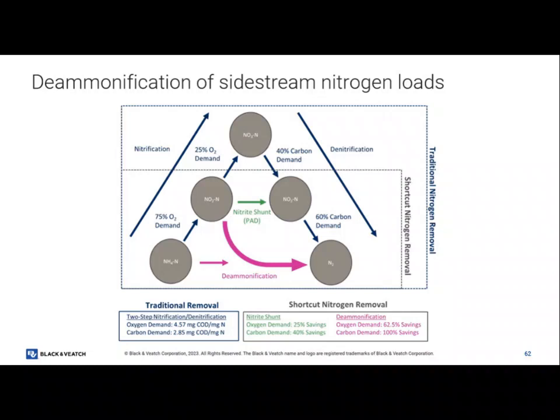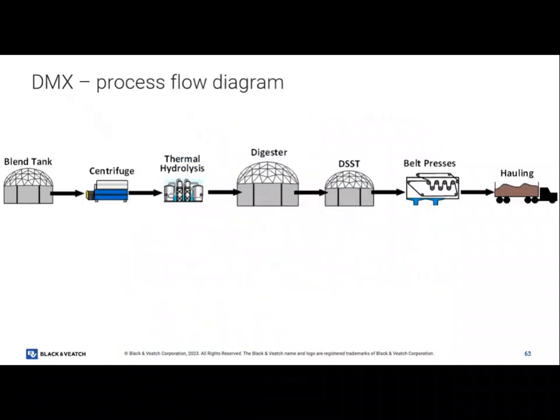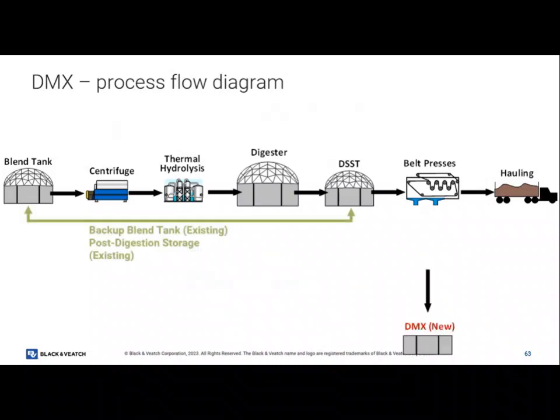When we talk about SRTs of this organism, normally we're talking 10-day SRTs in aeration basins. We're talking 60 to 100-day SRTs for these bacteria to grow. They're just very slow growers because there's very little energy in this business. Like when you think about electron transport, ATP that Paul talked about, there's not a lot of ATP to gain in here. And so they're living on very low ATP amounts.